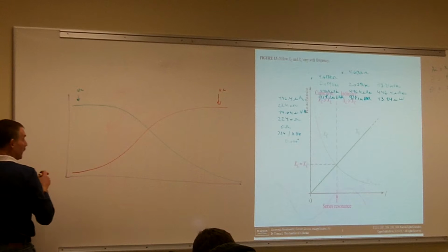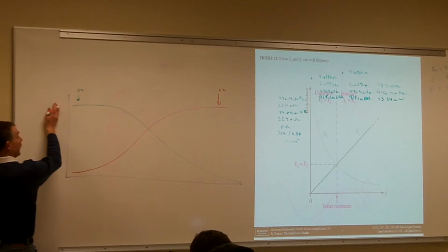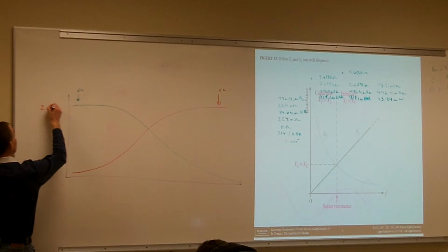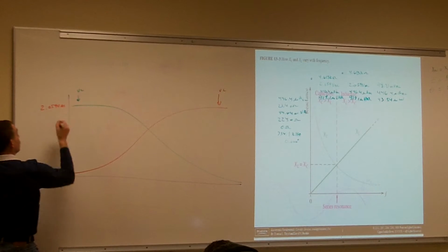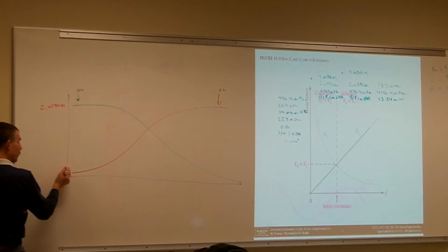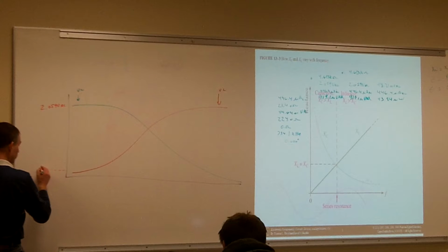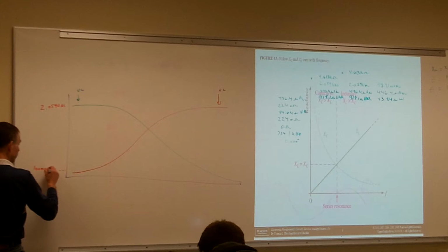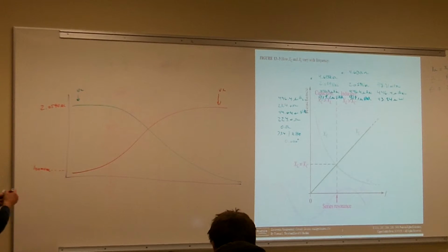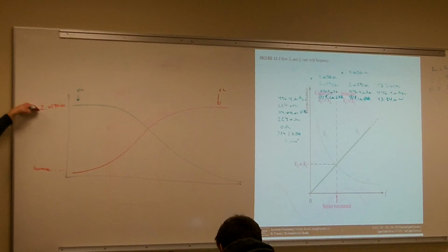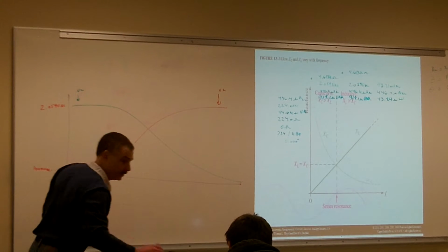So now when we're looking at it, we said that the voltage of our capacitor and the voltage of our inductor both went up to approximately 2.059 volts AC. Our source voltage is really way down here. This is where we're going to be at 100 millivolts AC. That's where our source voltage is. Here's the actual voltage of our capacitor and inductor. Let's see, I should change that up here.